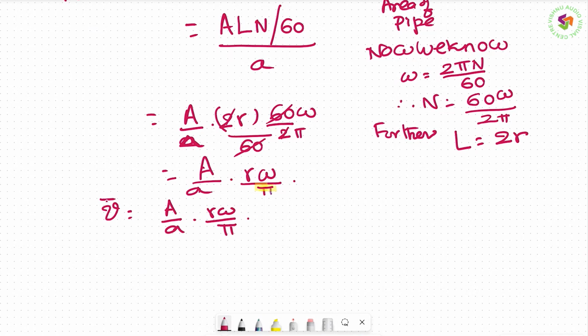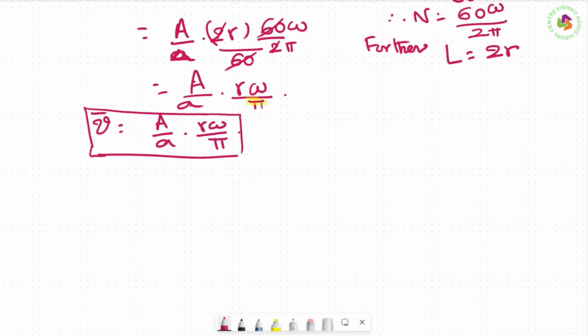So this is the first thing with air vessels, because when air vessels are fitted, the velocity is constant, equal to the mean velocity, because the whole purpose of keeping the air vessels is to maintain the velocity as constant. Thereby the velocity fluctuations are zero. Therefore, the acceleration pressure head is minimized and limited to only a small portion, and thereby the friction loss is also reduced.